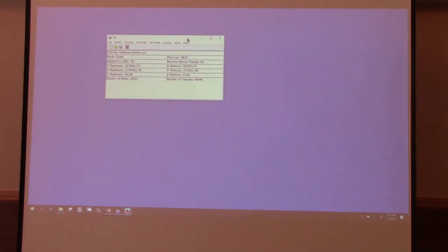Question about the border files. Is there any way to create them directly from a CAD entity within DXF? What I've done as a workaround is draw them in CAD, create CAD XYZ points, and then import those in. That's the only way I know. That's the only way, because the border file has a special format in it, which isn't much of a format. It's just XYZ points, and then the last point duplicates the first point, and the last point's inside or out, right?